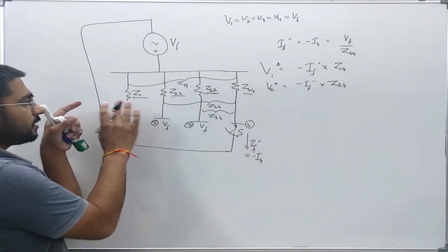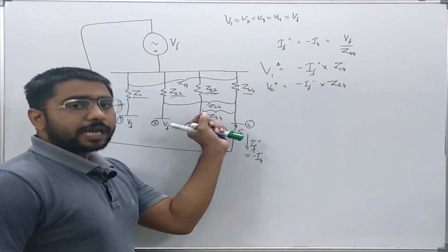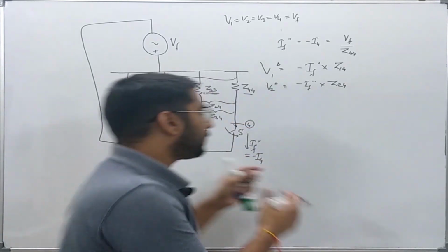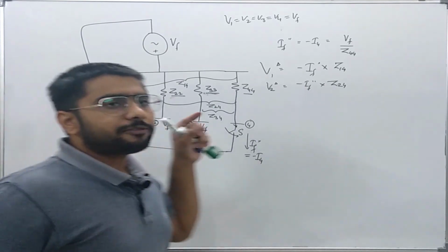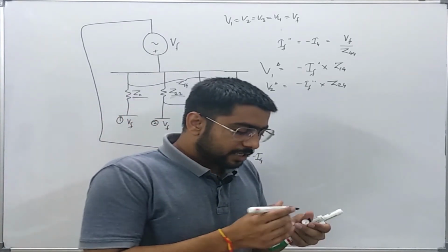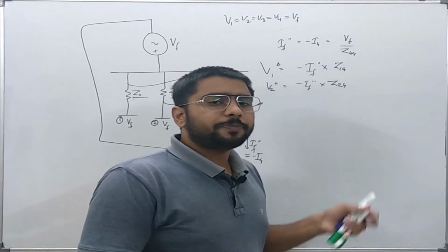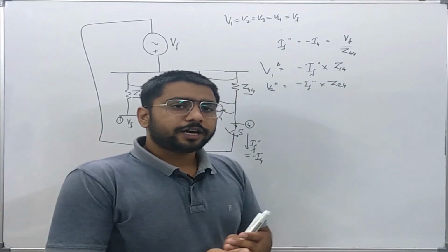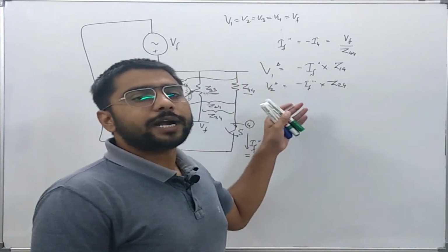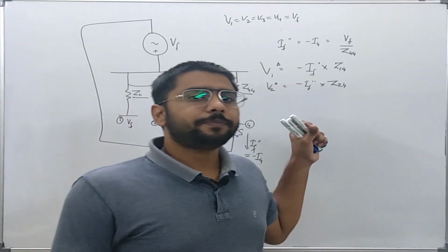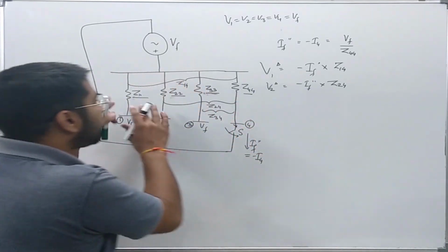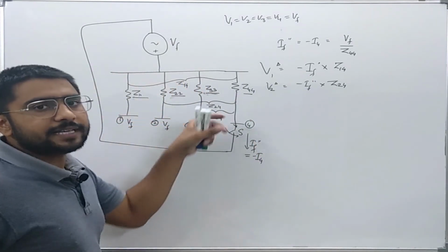So this rake equivalent network is a kind of physical representation of a network in terms of the elements of the bus impedance matrix. As I already told in one of the previous lectures, it is not possible to actually draw the physical equivalent network from the bus impedance matrix. This is the closest we can get in terms of the transfer impedances.